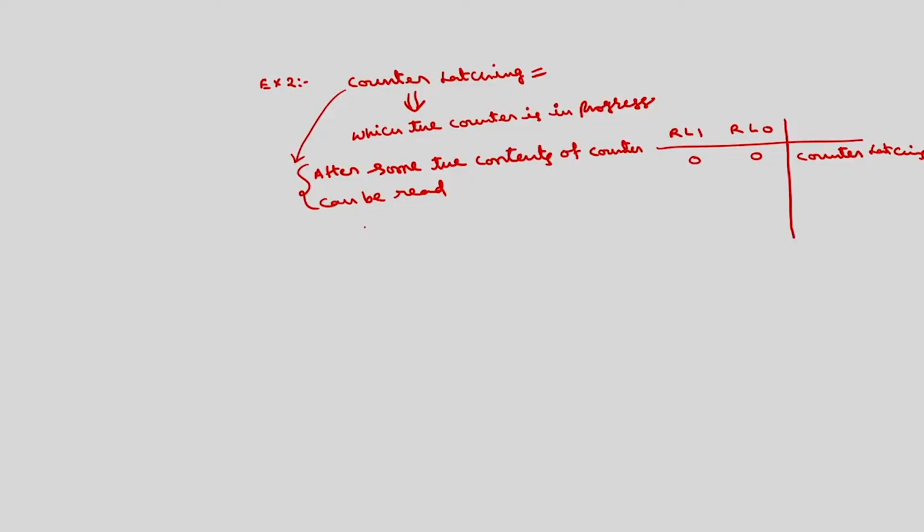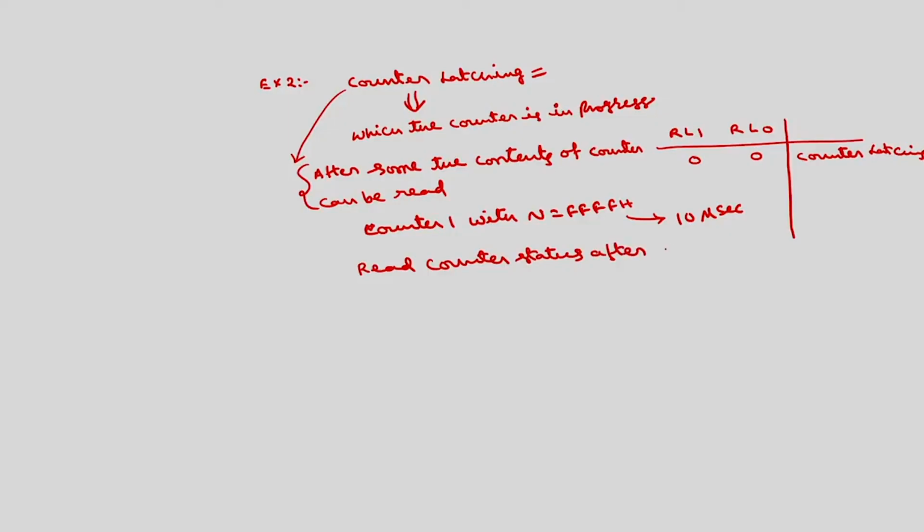For that, initially I will load counter 0 or counter 1 with a count value of FFFFH. Say this corresponds to a delay of some 10 microseconds, but I want to read the counter status after 2 microseconds. Okay.